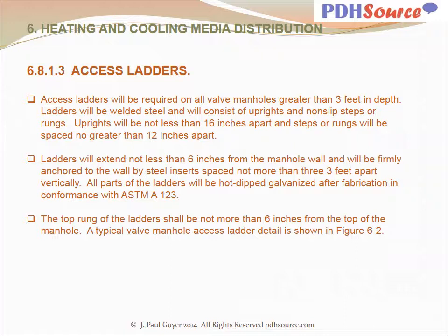Access ladders will be required on all valve manholes greater than 3 feet in depth. Ladders will be welded steel and will consist of uprights and non-slip steps or rungs. Uprights will be not less than 16 inches apart, and steps or rungs will be spaced no greater than 12 inches apart. Ladders will extend not less than 6 inches from the manhole wall and will be firmly anchored to the wall by steel inserts spaced not more than 3 feet apart vertically.